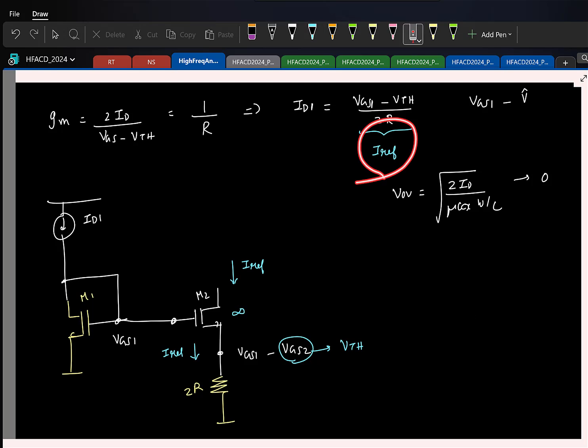That's step 1. Next I have to make sure that I go and compare my bias current with this reference current and change this guy so that these two currents become equal. Fine. So I have the reference current here. So to subtract this current, what should I do here? Remember, I have IREF.